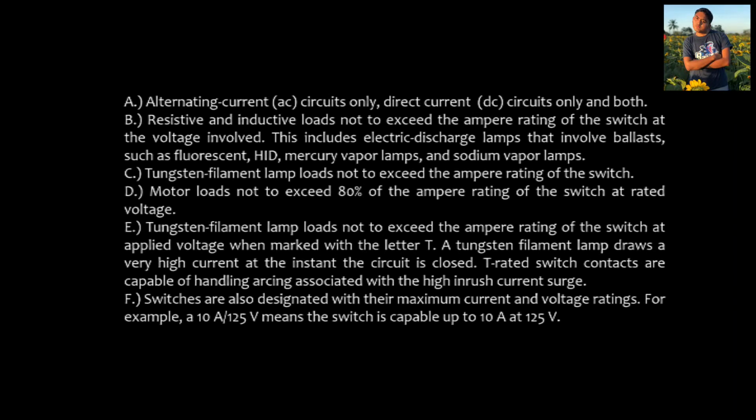Yung mga switches daw po ay designated with their maximum current and voltage ratings. Yung example po niyan is yung 10 ampere over 125 volt. Yung rating po na to ay ginagamit para sa safety and also yung cable po ay gumagana ng mas maayos kahit gamitin yung maximum capacity of your power supply.